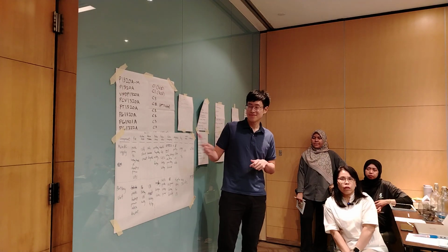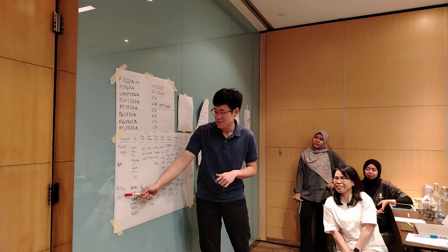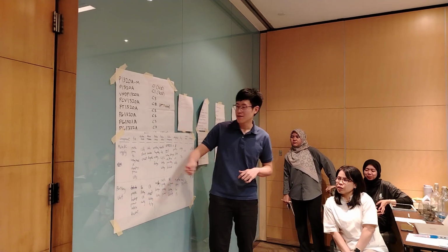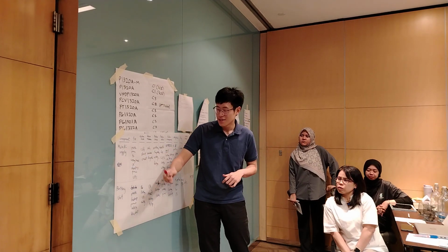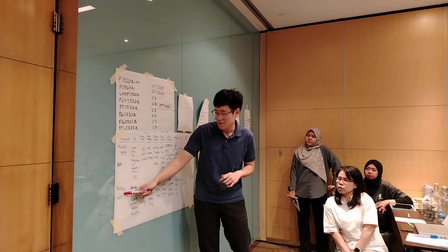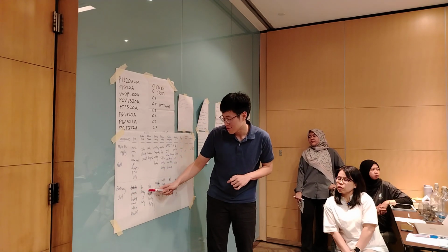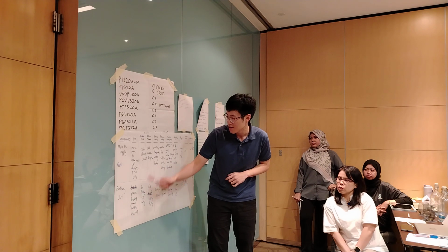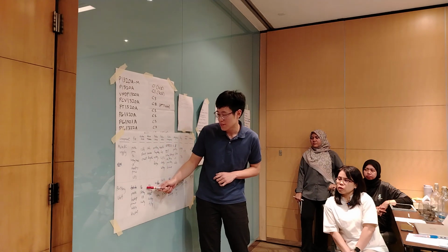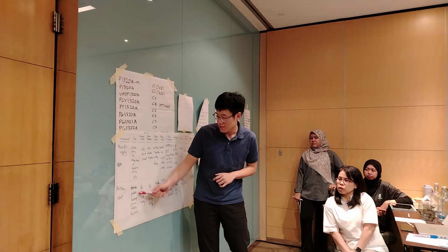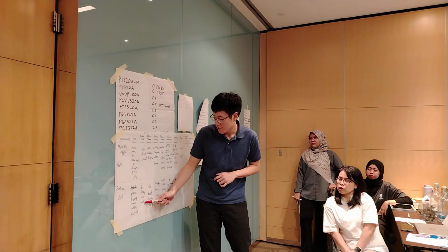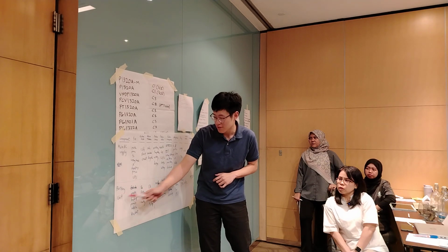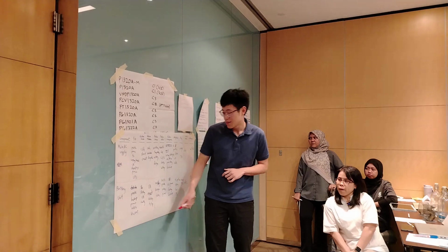Okay, next the battery unit. Since we mentioned that when the main AC supply fails, the battery will be supplying the power. The battery unit's function is to provide backup power during the blackout. The failure mode we're considering now is that the circuit breaker for the battery is faulty. So basically the battery is healthy, but the circuit breaker is faulty.